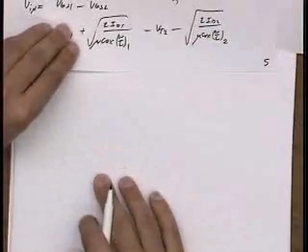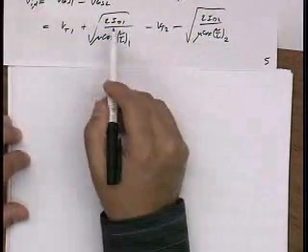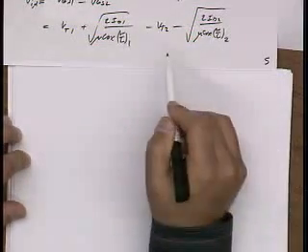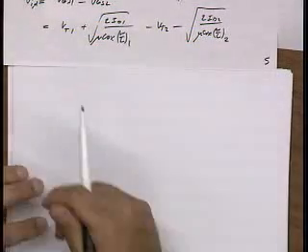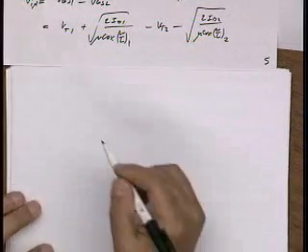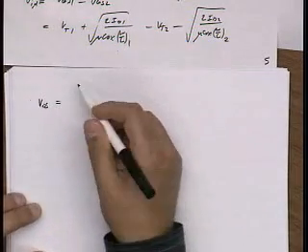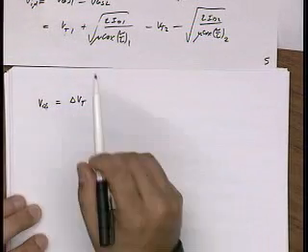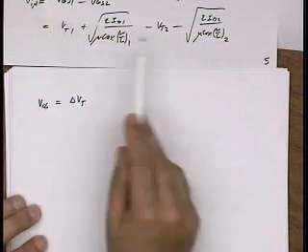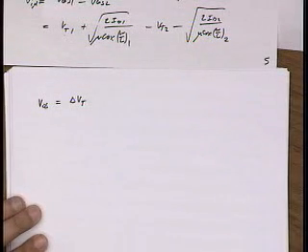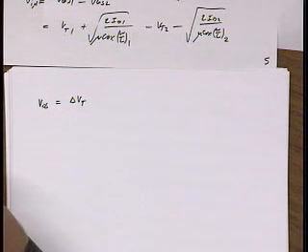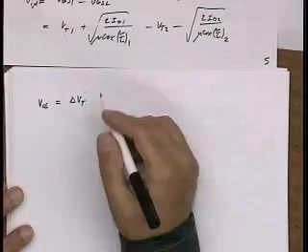Okay, so the name of the game is to substitute average value plus or minus deviation, average value plus or minus deviation, and then say the deviations are small, and then simplify things to linear terms, right? So therefore the offset voltage is first of all a delta VT, and that actually hurts, right? The fact that the offset voltage is directly proportional to the difference in threshold voltage is one reason that offset voltages in MOS technology are considerably higher than bipolar technology, because threshold voltage varies a lot.